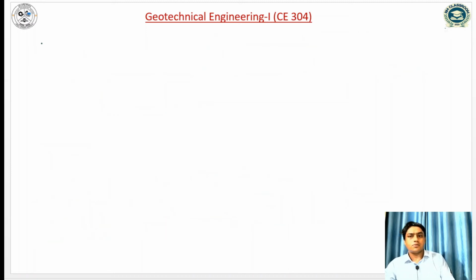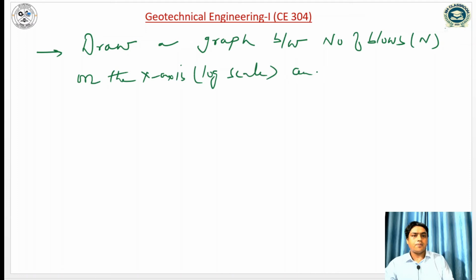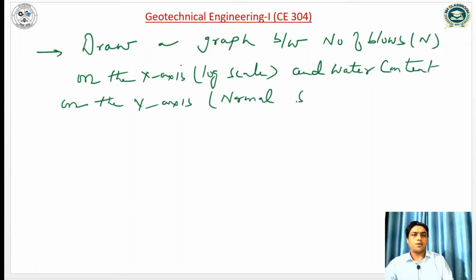with the help of these observations, draw a graph between number of blows on the x-axis, log scale, and water content on the y-axis, normal scale.